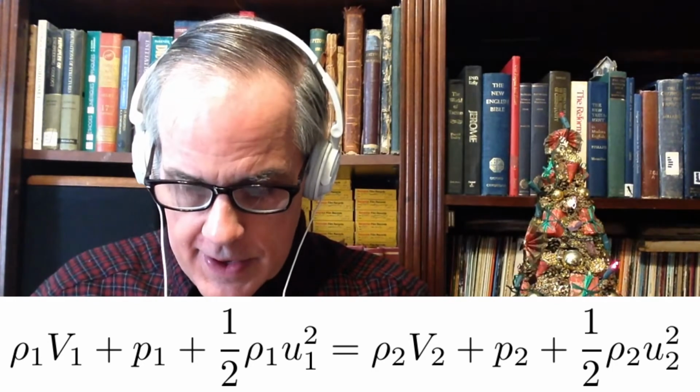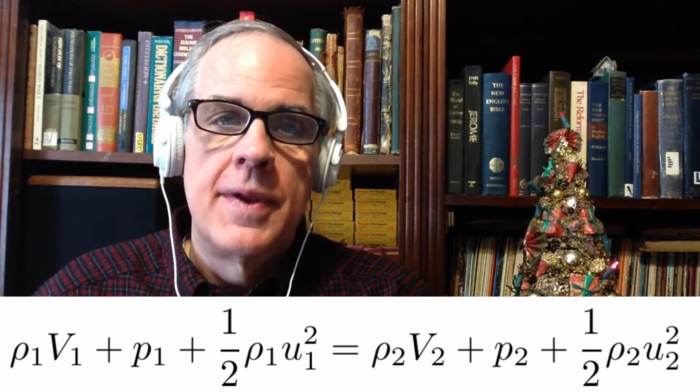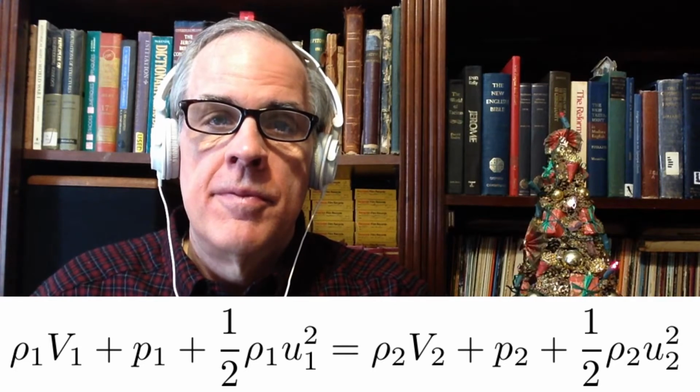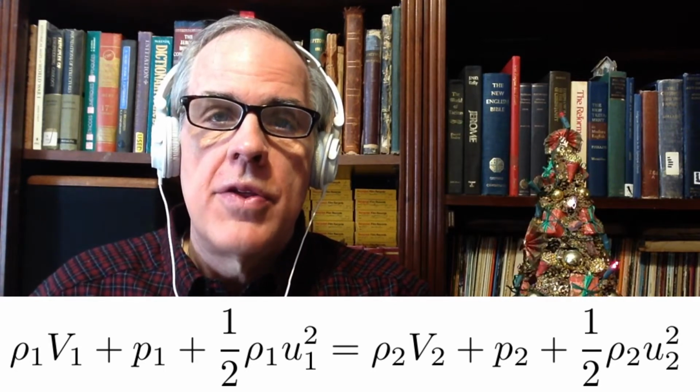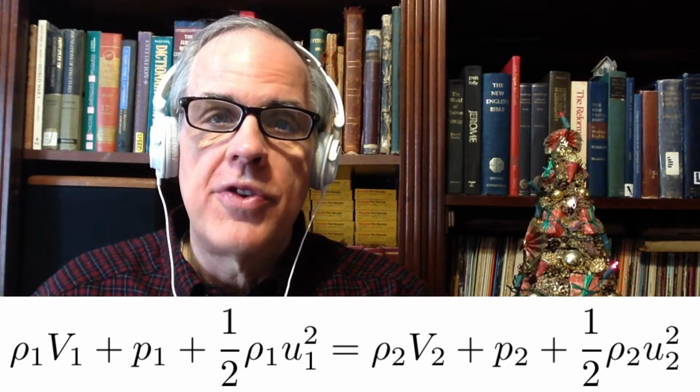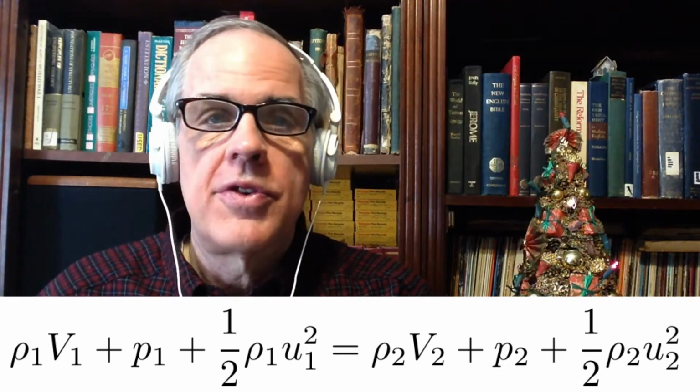And so the last one is velocity or kinetic energy, the fluid in motion. With those three, we basically say that the sum of those energies at state 1 is equal to the sum of the energy at state 2. We're also going to assume, since it's incompressible, that the two densities are the same. With that out of the way, we do a little math and we end up with an equation that basically has only pressure and kinetic energy.